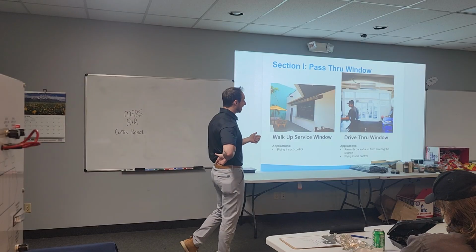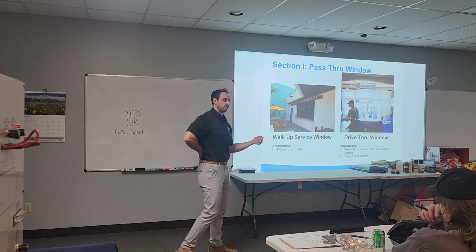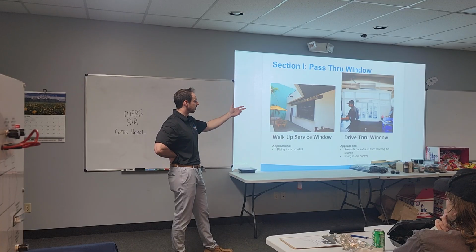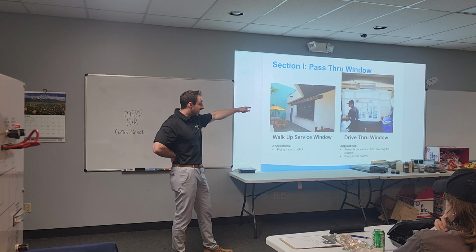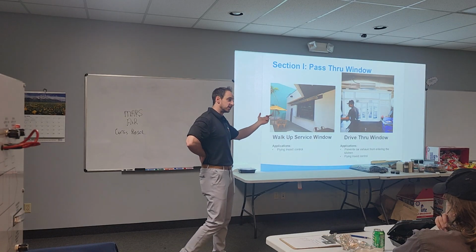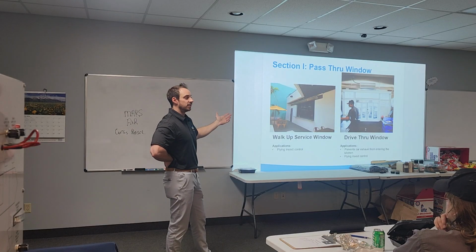And the reason why I say that is they might still have problems. They've got the air curtain over the back door and they're claiming, hey, I still got flies in my kitchen, still having problems. A lot of times it's the other openings, and a lot of times it's specifically the drive-through window, because those open up directly to the kitchen, but it's just something they don't think about.